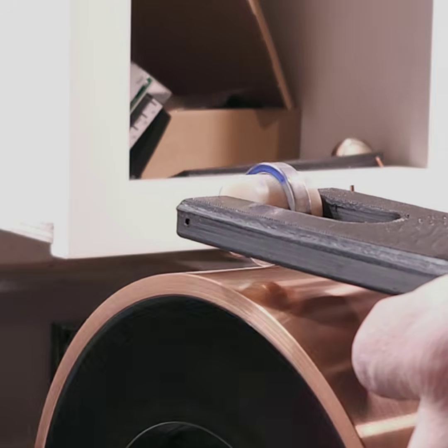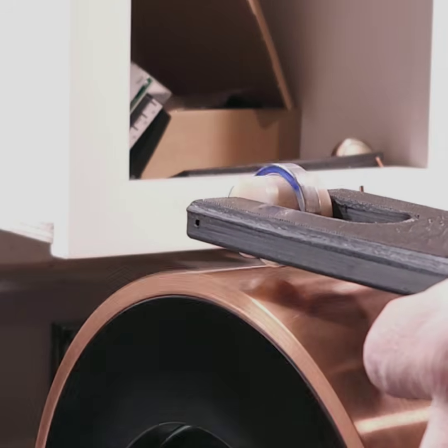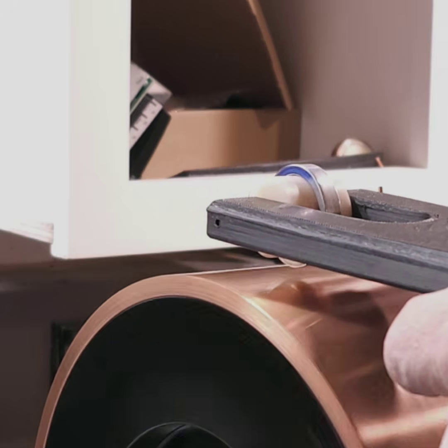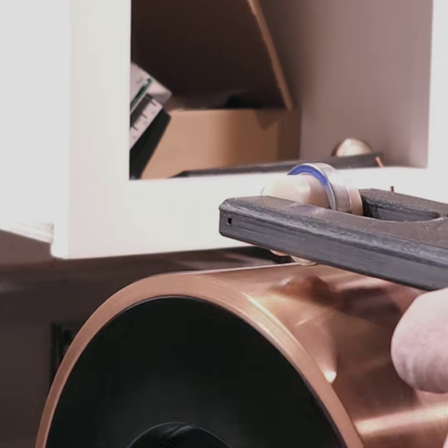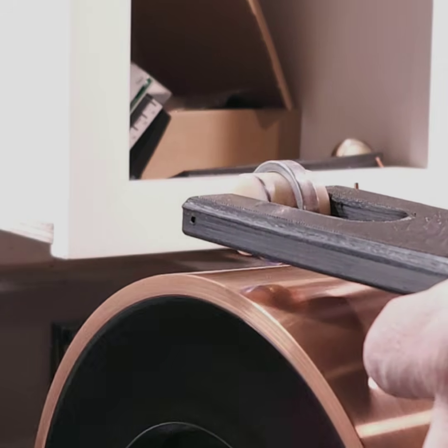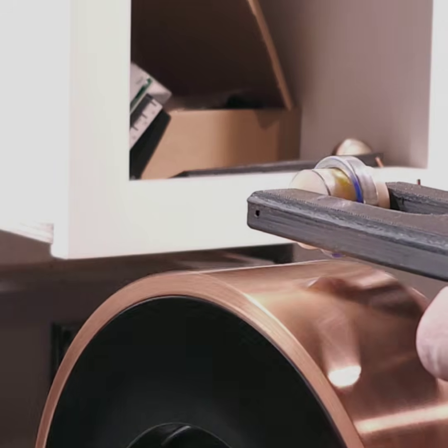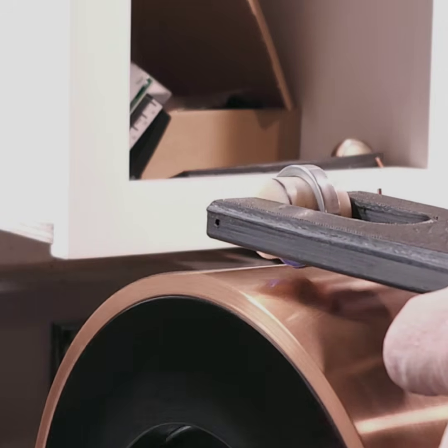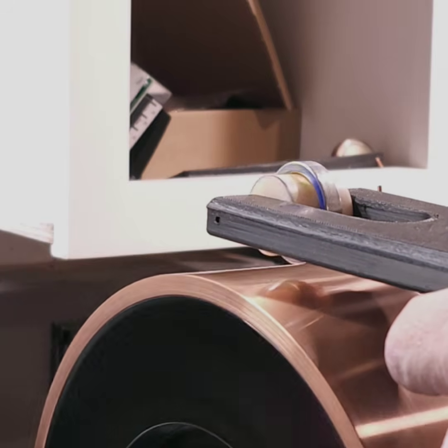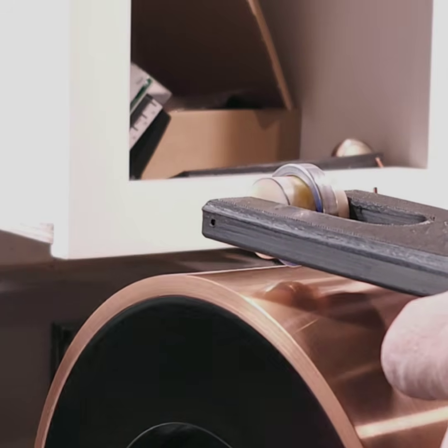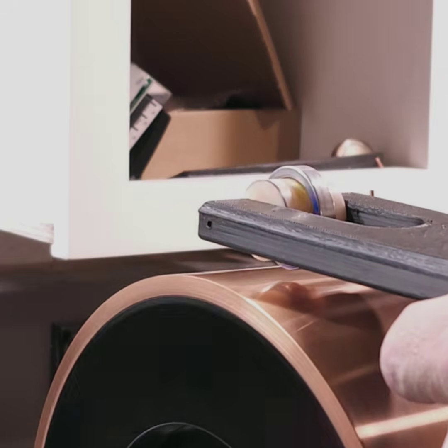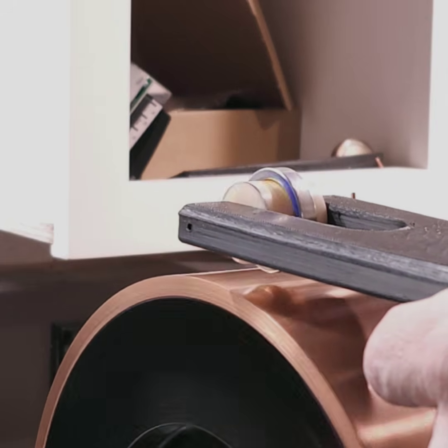Now, as you can see, this continues to go as long as that stator is moving. The eddy currents are making that ring spin. I'm not clicking against the copper, try not to, but it's not the copper grinding against that magnet that's making it spin. And I can physically feel that, oh, there we go, it's spinning pretty good now. I can physically feel that eddy current rotating that and pushing against me, but it's not like it's causing drag.